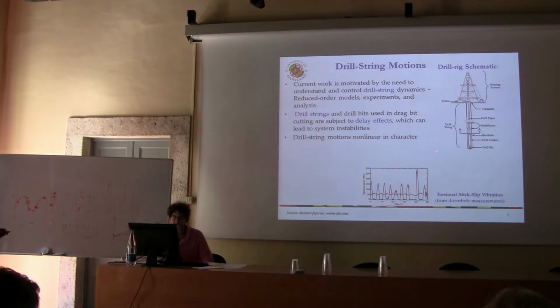To put things in perspective, all the control is typically right at the top, and all the motion that you need to control the drill bit is out here. It's almost a kilometer away from where your control is, so it's a non-collocated control problem. And in addition, the sensing that you have is not readily available. You do have sensors at the bottom. And so this is a recording of a torsional strain provided by Schlumberger.